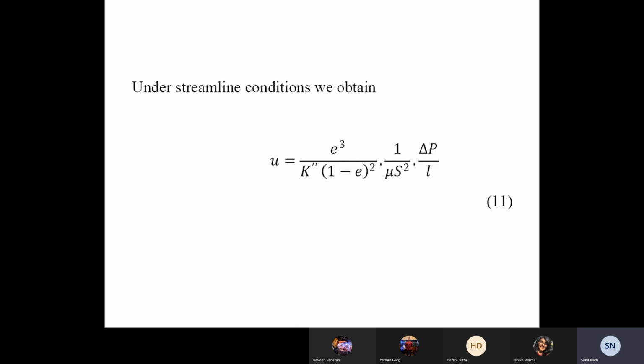What is the length of the fluidized bed? What is the point of incipient fluidization? At what fluid velocity does that happen? What is the force balance under that incipient condition? Because that's only when we can do that balance exactly. And then what sort of pressure drop is there in that bed? So we can extend this analysis to a number of other industrially important cases.